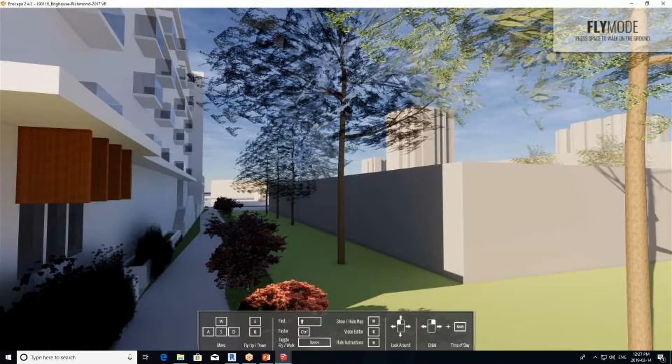The nicest thing about this is that when you are working with Revit and you have consultants that are also using Revit, rather than Lumion, where whenever you make changes you have to update constantly, with this one you just load it in and it's automatically generated based on whatever material you put in. For time's sake, Lumion requires extra setup, whereas Enscape, you don't have to do that. Whatever materials you put in here are going to get generated inside Enscape. Whereas Lumion requires a little bit more setup.